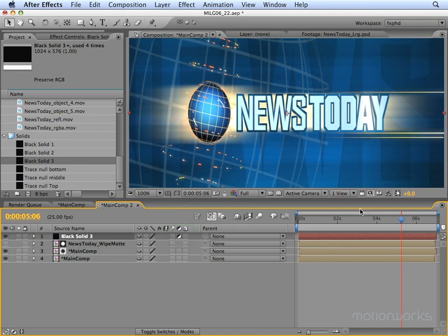Now very often what will happen, because TVs are made of fields, each row of pixels, and a television works by scanning down these in alternate rows, so this is why we have fields. You have upper and lower field, and the original reason for this is because when TVs were first created, the scans were pretty slow, so the guns would fire at the tube and it would scan down from top to bottom, and what would happen is the top of the screen would start to get slightly dark by the time the guns had reached the bottom, so you would see the scanning on the screen.